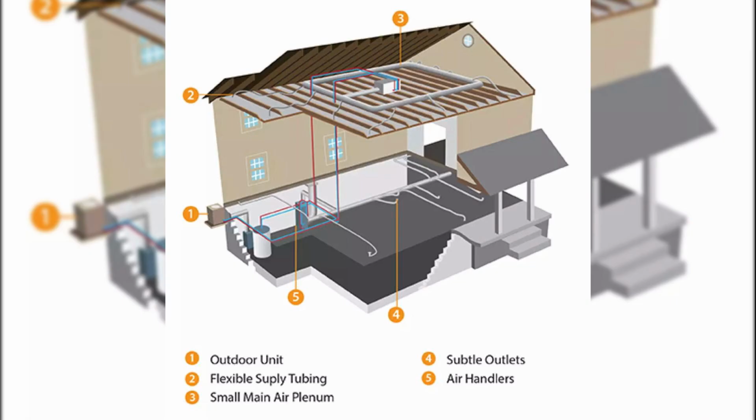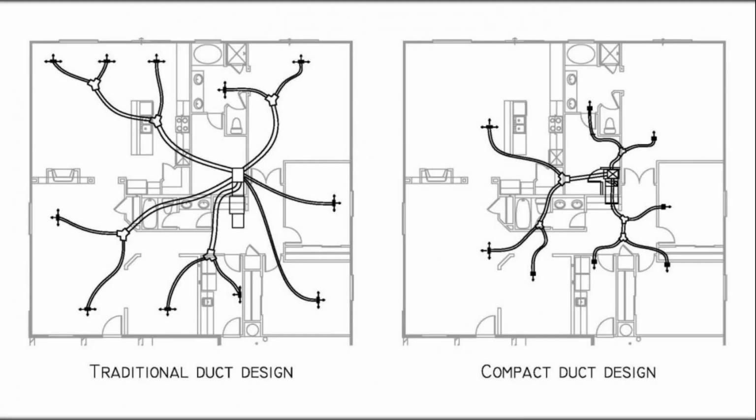Compact duct system. Another strategy is compact duct design. Compact duct systems with consistent duct lengths provide more uniform air delivery temperatures. Low-mass duct systems, flex duct and ductboard, show much less temperature variation between registers than all-metal systems. Temperature differential across registers can cause comfort issues even with correct airflow.